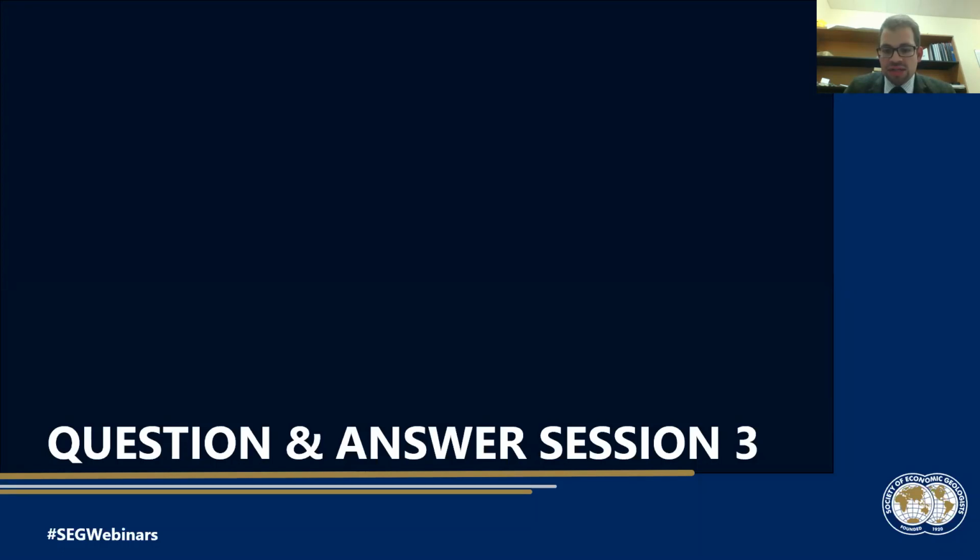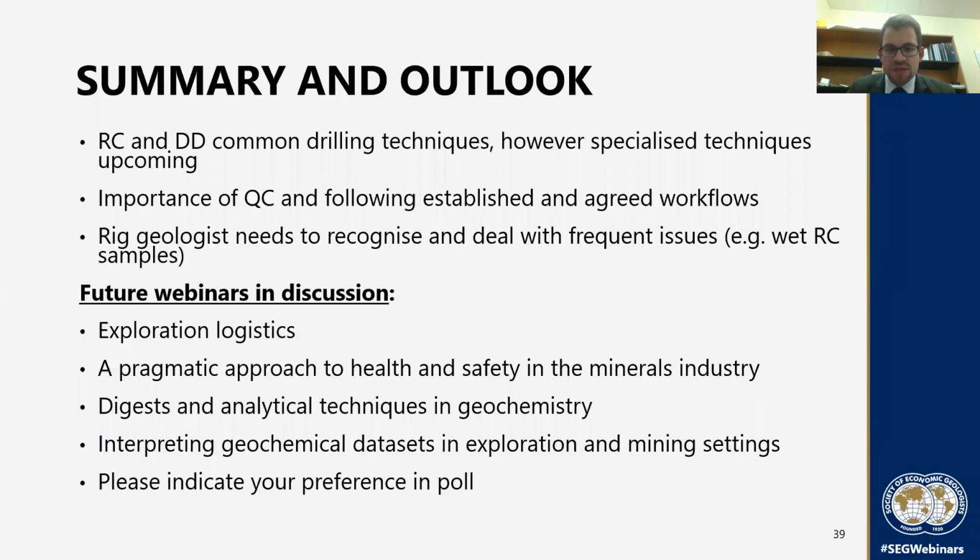Great. I've got a few more slides here, but that brings us basically to the end of the webinar. To quickly sum this all up, during this webinar we've learned about the different drilling techniques, about some of the specifics like auger drilling or coiled tube drilling. I haven't talked about that too much, but I focused on reverse circulation and diamond drilling, because those are the ones that have been used for a long time and are currently the main drilling techniques in use.